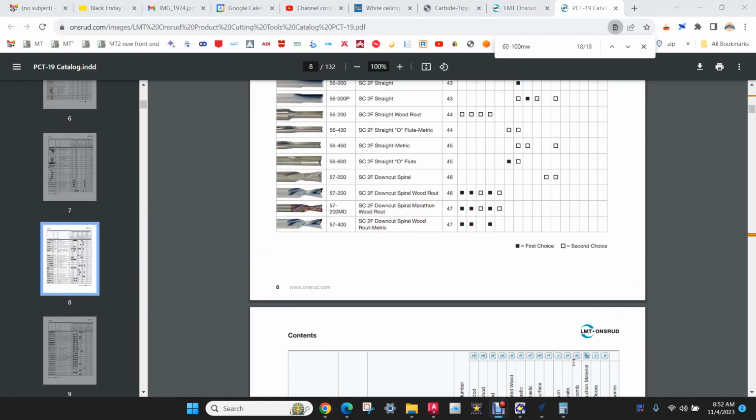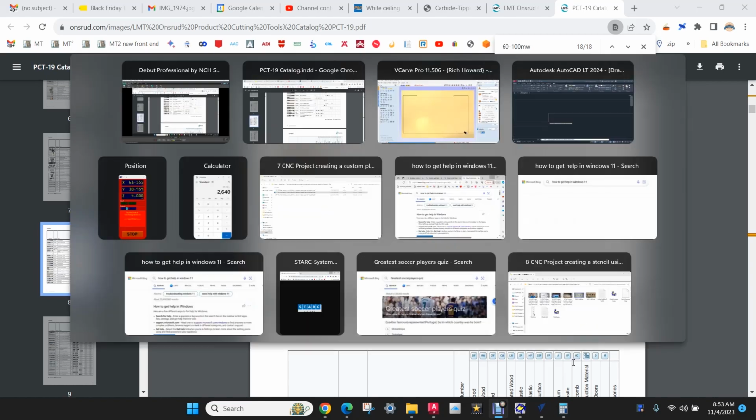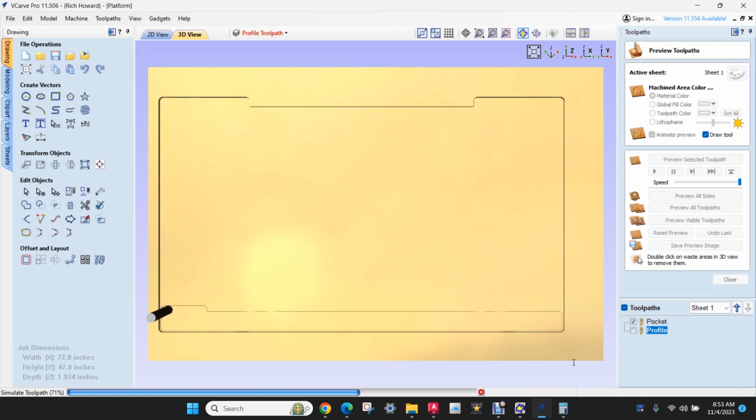So the way that I remember it is an upcut is going to be clean on the down or opposite side. I'm going to want downcut because I want to be clean on the side that I'm cutting, but I'm probably going to experiment with both since I have both. I want to minimize the amount of work necessary. I'm wondering, this is taking so long that I wonder if this has unintentionally selected the wrong bit. Perhaps not, but longer than I'd expected.